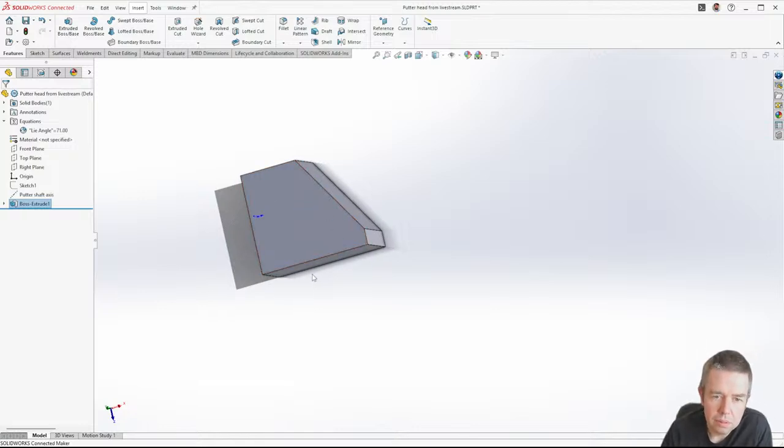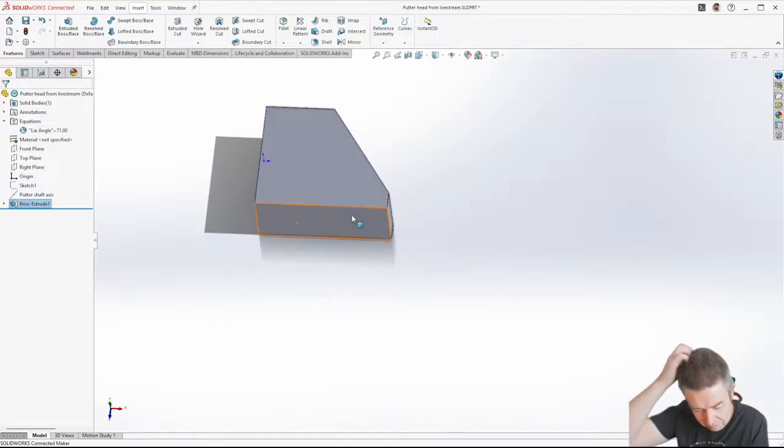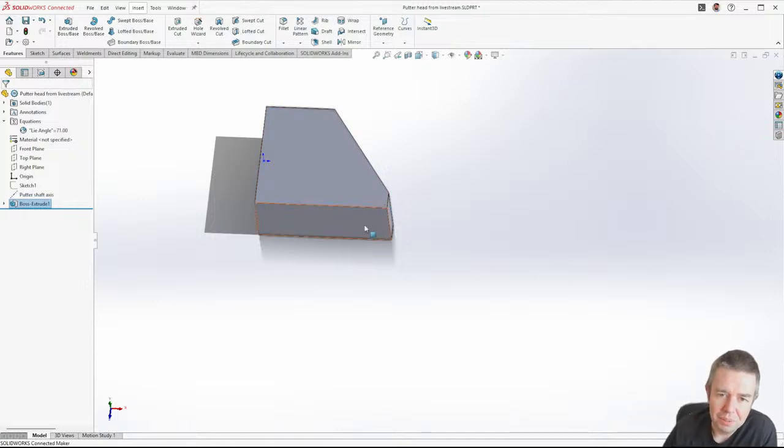Now, for general safety and usability of the putter, for safety reasons, you don't want to have sharp edges on things. They also don't survive shipping. So although you can mill something to this shape, it would hurt you if you tried to use it. It would damage the other clubs in your bag, and it would not survive in this form.